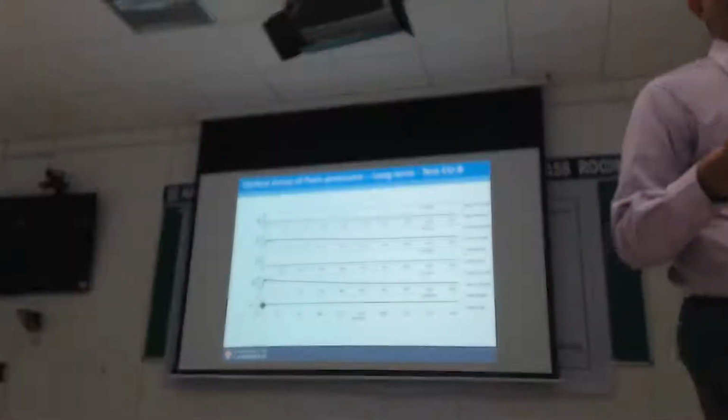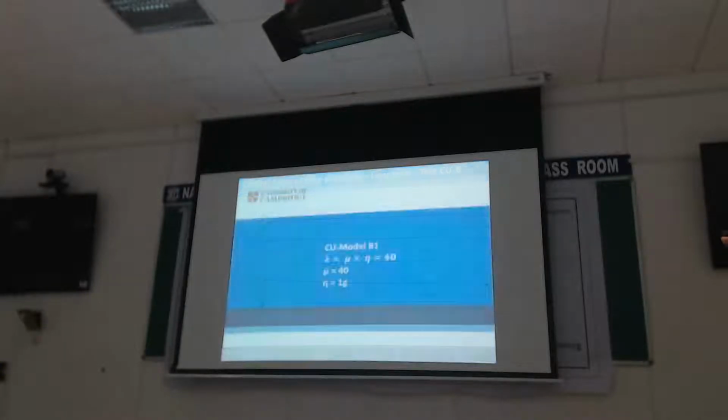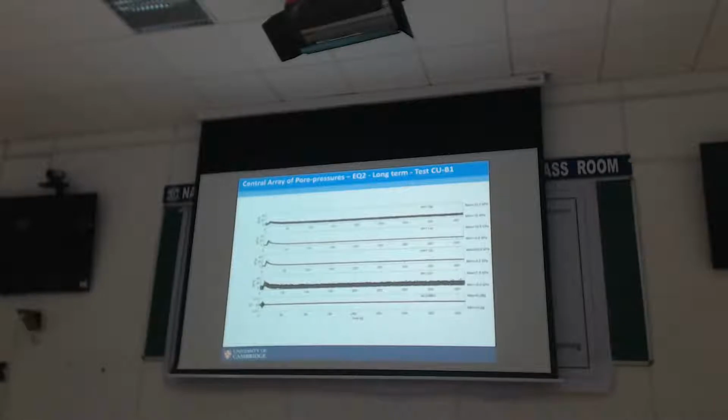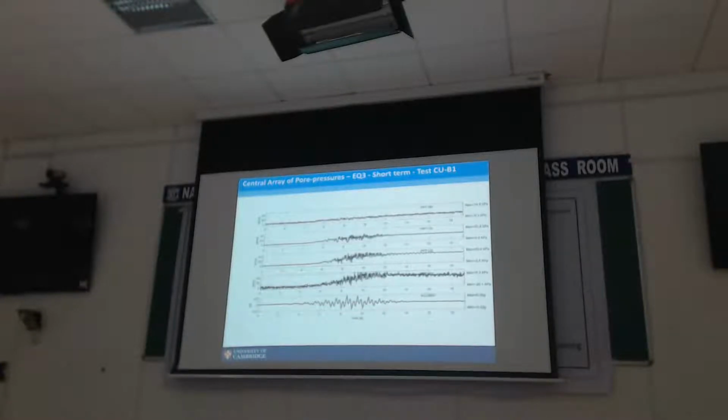And this is the problem, which means that the pore pressure builds up, and we think, okay, but before the slope can move, the pressures are gone. And that's why the slope wasn't moving when we were hitting with the right size earthquake. We had to hit it harder and harder. And you could confirm this for the other area as well.